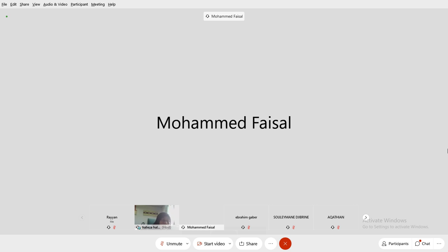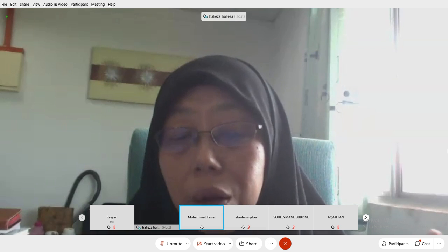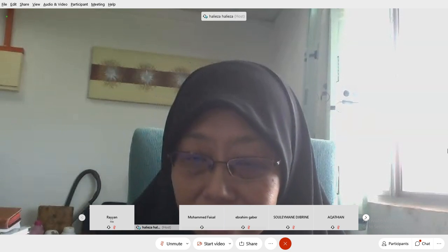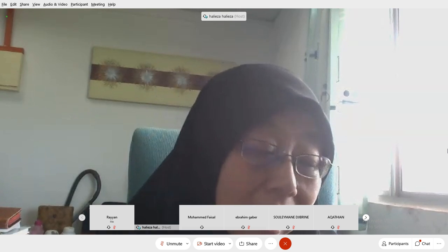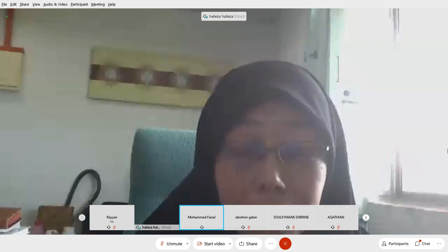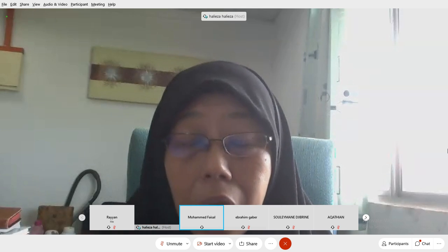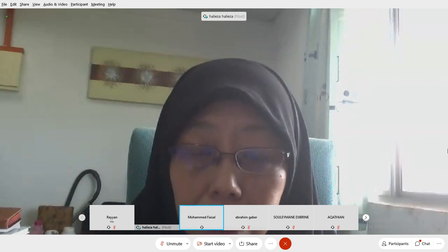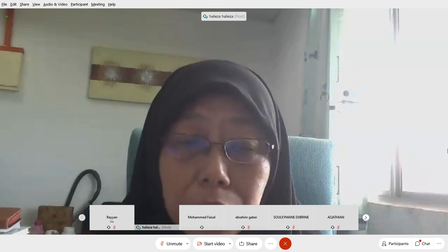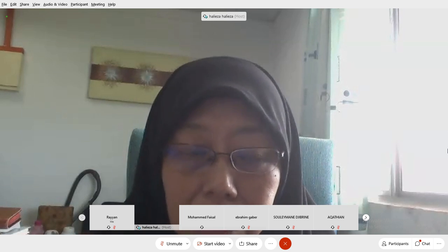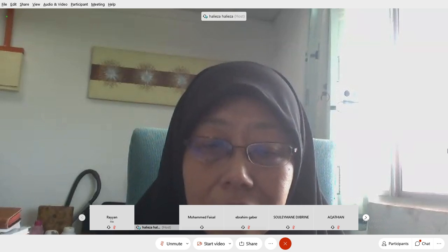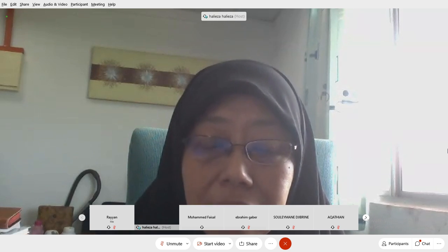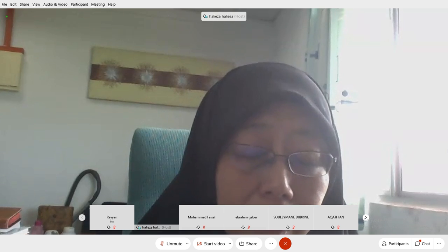Oh, you did the calculation wrongly. We did not move the Q to the other side. That's what I mean. If the Q is negative, it will be positive. Okay, redo for the rest of you guys. Solve for the work. Bring over the Q, everything to the right hand side. Q is going to be on the left hand side. See whether you're going to get the same answer. But it has to be negative, obviously.